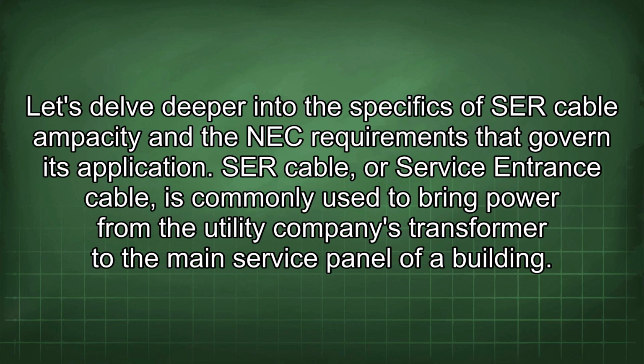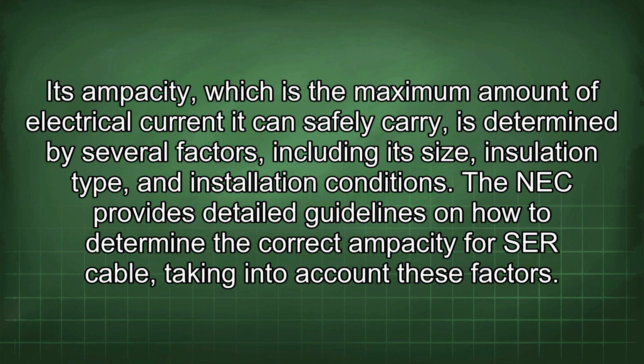Let's delve deeper into the specifics of SER cable ampacity and the NEC requirements that govern its application. SER cable, or service entrance cable, is commonly used to bring power from the utility company's transformer to the main service panel of a building. Its ampacity, which is the maximum amount of electrical current it can safely carry, is determined by several factors, including its size, insulation type, and installation conditions. The NEC provides detailed guidelines on how to determine the correct ampacity for SER cable, taking into account these factors.